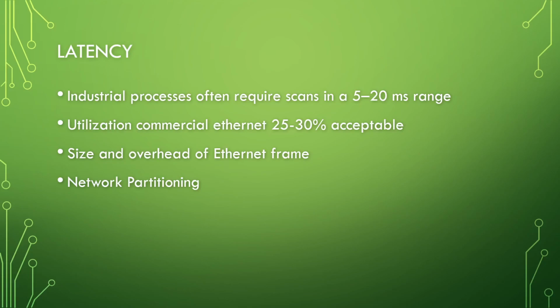Well, if I have an industrial PLC that's my safety PLC monitoring all the inputs and outputs, you press that e-stop button, you don't want to let it go 100 milliseconds before it's like, "Oh, wait, that person's finger's getting cut off, I should stop the system." No, you hit that e-stop, you want that thing to respond instantaneously. So that's that whole 2 to 5 or 5 to 20 milliseconds. We got to keep that down.